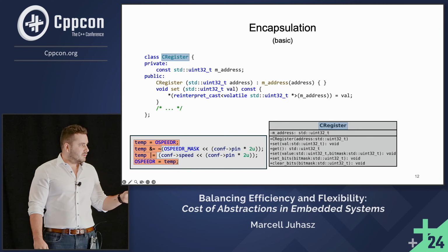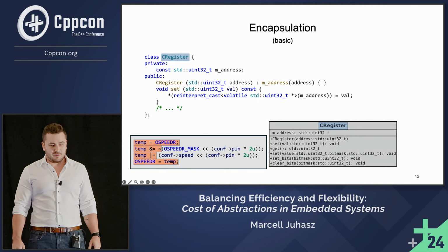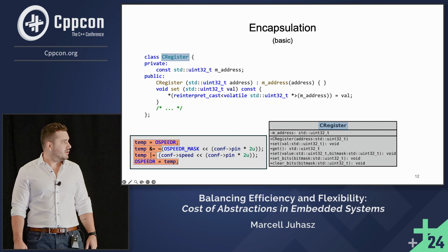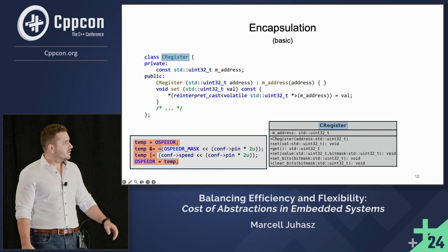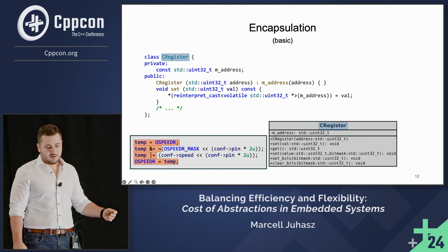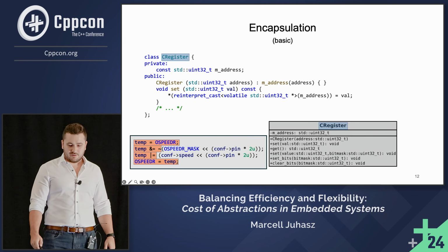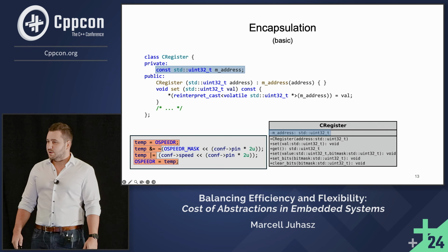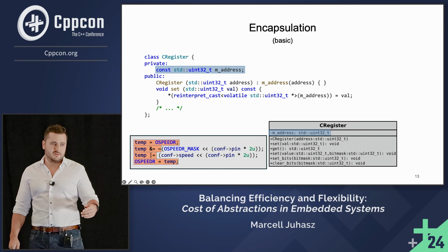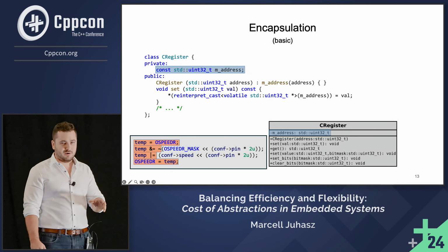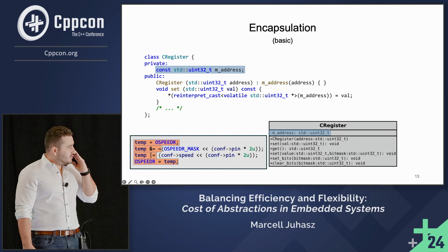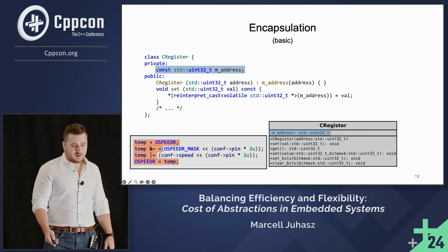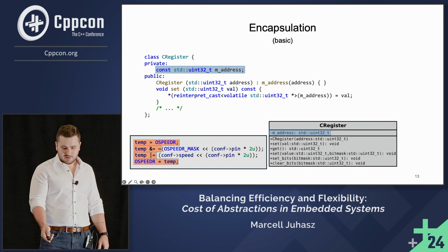Now, I want to show you swiftly an implementation. It's a simple example implementation so that we all understand what I mean here. Let's start with the C-register class. As I have said, this is the class for the basic register operations. Every register is mapped into memory, so every register must have an address in memory so that it can be accessed via a simple memory access operation. In this case, this is solved with a private member variable of an unsigned integer.